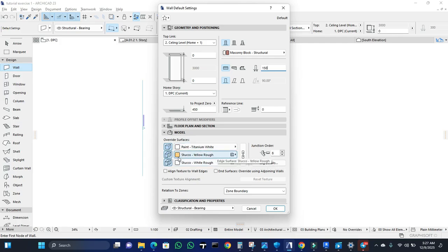Well, if you don't want to set distinct materials for those, you can just link the 3 materials, because we know that it's walls. So if you click on this chain here, it's going to use the first material you set and apply it to the rest of the materials. So that's it. I always like linking the materials, so I don't go about setting each individual surface, except I want to achieve a different effect on a particular area. That's where I unlink that area to set the material. I hope I made myself clear.